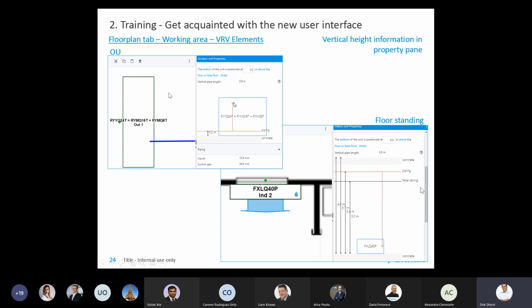Actually, in this picture, the outer unit is put upside down. The connector is not on the top of the outer unit. It's somewhere here at the bottom of the outer unit. So the vertical pipe length will not be 80 centimeters. I think in reality it's only 10 centimeters above the pipe run height, which is in turn 20 centimeters above the floor of that roof.